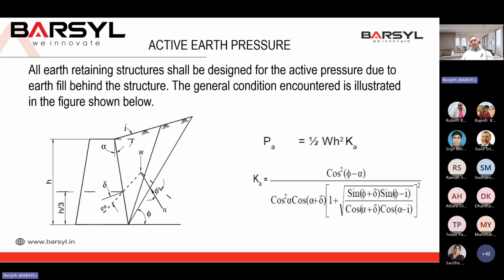Next, major force. Whatever I explained so far is from the superstructure and the self weight of the structure. The other additional major force which is acting on an abutment is the earth pressure. You all might have seen that abutments are retaining the earth fill behind it. So earth always exerts a pressure on the abutment, and that will act as a lateral force on the stem of the abutment. It is like the stem of a cantilever retaining wall. The abutment wall will act as a cantilever retaining wall stem.